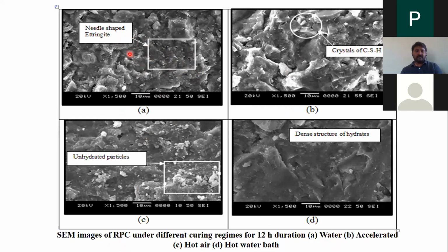This one is the water cured sample for 12 hours of duration. Ettringite, you can observe; the magnification is 1500. All the magnifications are the same, because if you want to compare things, the magnification should be at the same level. Ettringites we can observe for water bath curing.